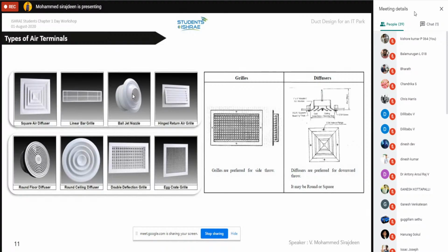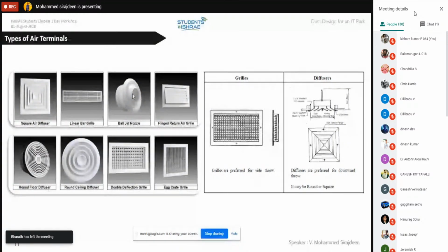How the false ceiling provides availability, the same kind of availability is provided under the floor. They will raise a floor by using structural rods and supports. Around 500 to 700 mm of floor will be raised like a false ceiling. That is called false flooring. So there will be a vacuum space under the false flooring.